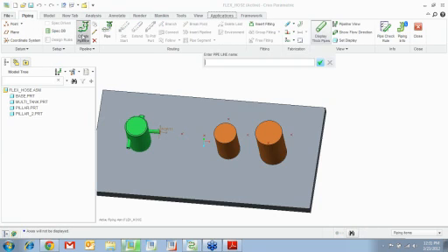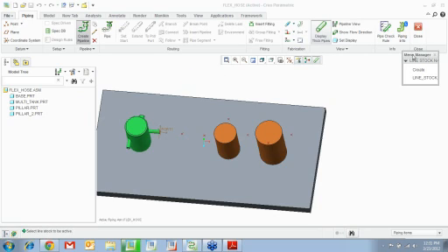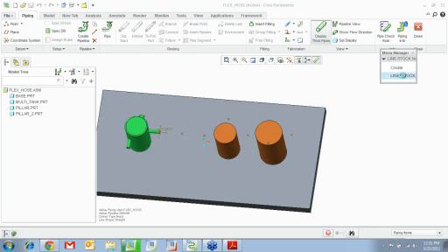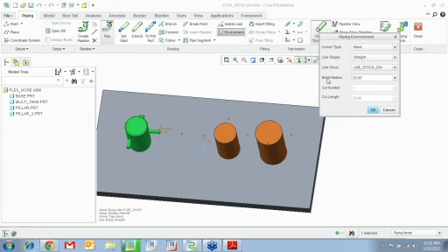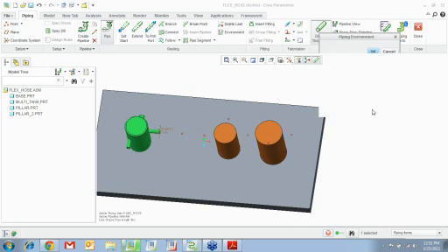Now I want to create a pipeline. You want to go ahead and set it a name. I want to use the line start. I go into environment, and I want to make sure that my line start is flexible. I can set a length and say this is how much I want the length to be, or I can go free. Okay, and say okay.